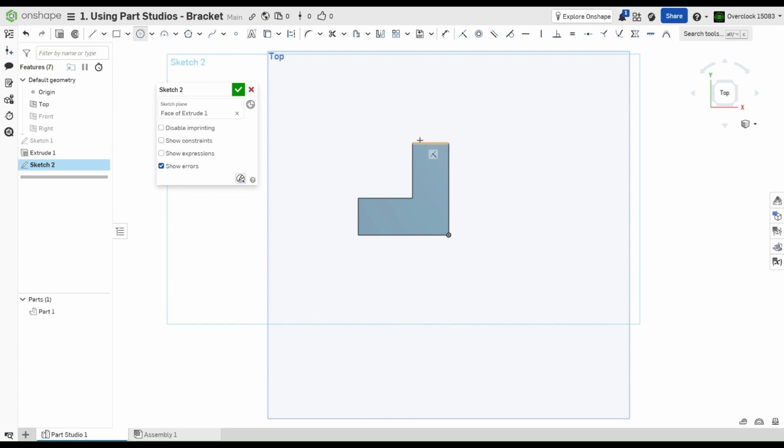And then you want to also align with the center of this, so you'll hover along it until you find the center, and then travel down. And this will have two lines that'll show you exactly where the center in that corner is, and you can just click and create a circle there. And this circle, we want to dimension this circle to be 3 millimeters. So just use the same dimension tool and just click on the outside. You don't want to click on the center.